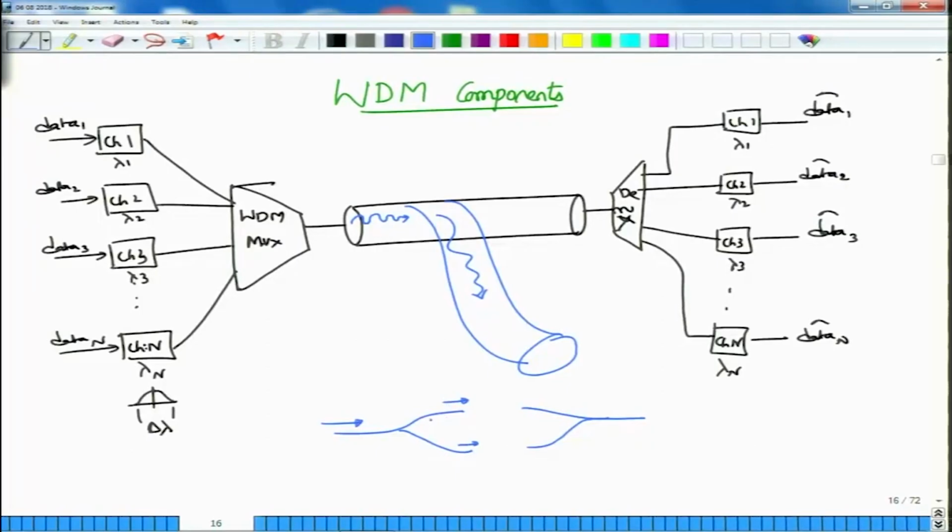So this, for example, is maybe say Delhi to Kanyakumari. This is the optical fiber that we are using there. But if I want to send the signal to say Jaipur, this would be the fiber that I have laid, which will carry signals from Delhi to Jaipur. So the WDM signals that are propagating from Delhi to Kanyakumari, if some of them have to be routed to Jaipur, one way would be to copy the entire stream. There are better ways of doing this, which I will tell you.